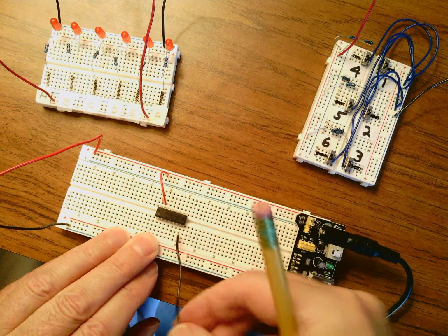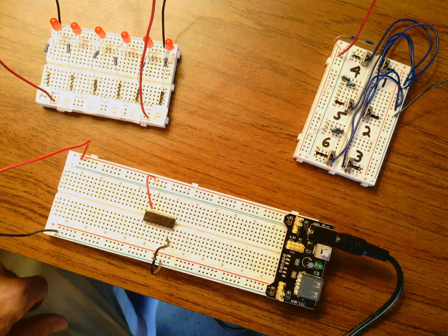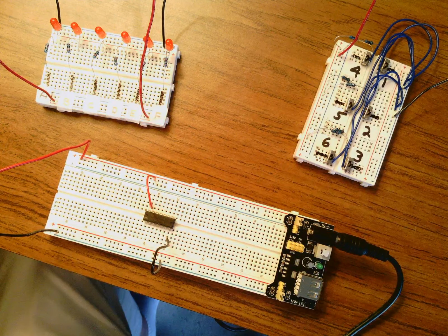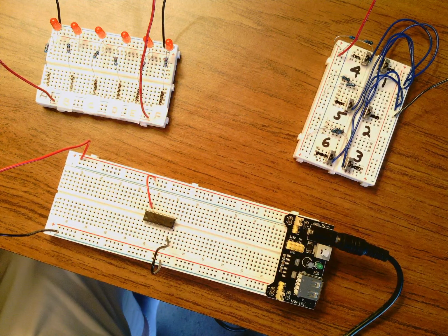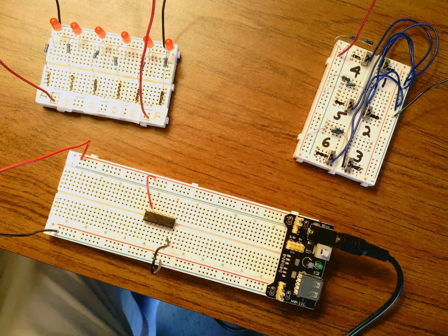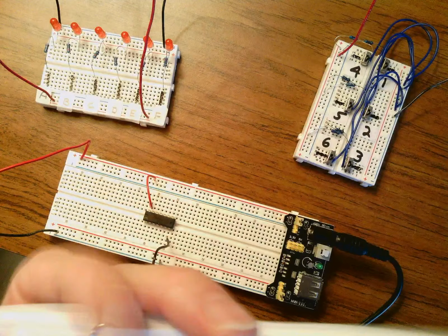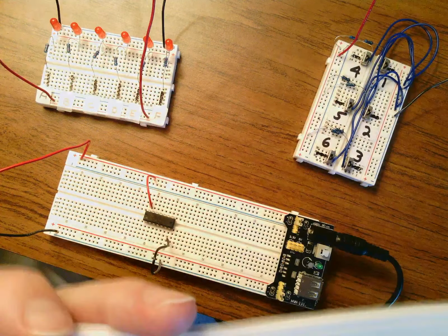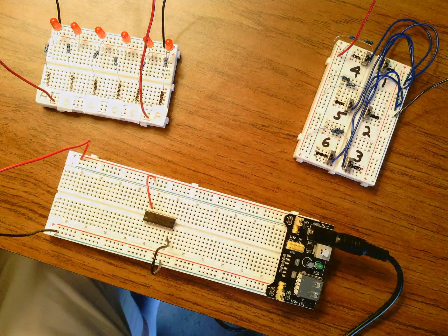Now, how do you know that pin 14 was plus 5 volts, and how did you know that pin 7 was ground? Because you'll have TTL specifications that I'm going to send you that look like this. It's National Semiconductor's manufacturer's data sheets, TTL specs. This is going to be put in the back of your notebook. I want you to get it printed out, double-sided if you would. I'll try to do it for you. But I'd like you to get it at the appendix or the very back of your lab notebook